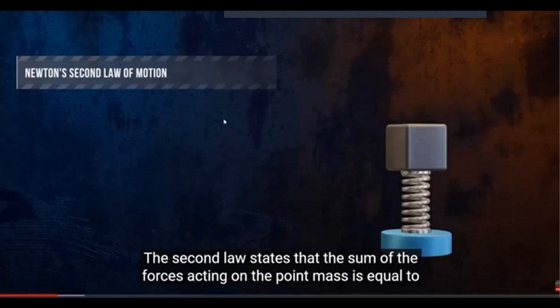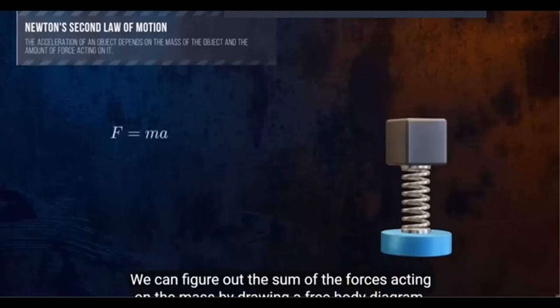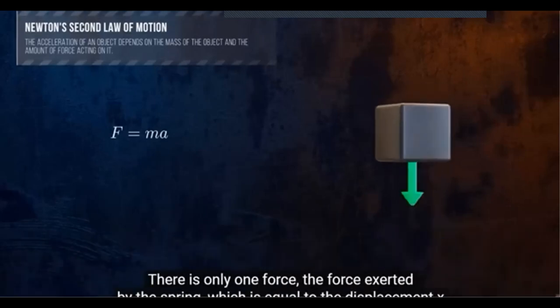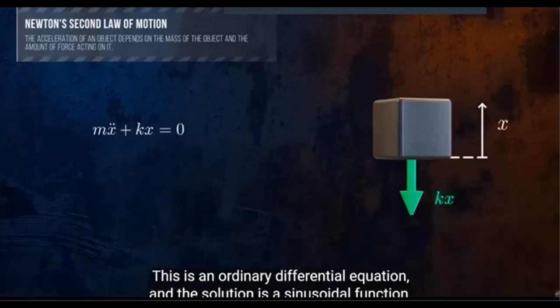The sum of the forces acting on the point mass is equal to the product of its mass and its acceleration, F equals ma. We can figure out the sum of the forces acting on the mass by drawing a free body diagram. There is only one force, the force exerted by the spring, which is equal to the displacement x multiplied by the spring stiffness, k. And so, we obtain the equation of motion for the system. This is an ordinary differential equation, and the solution is a sinusoidal function.